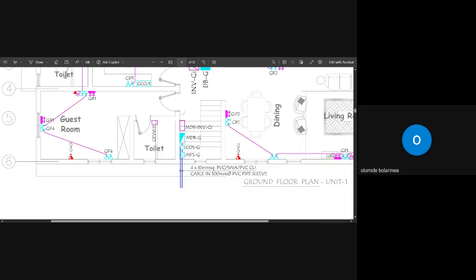Do you see where they wrote our metering system? You know that mostly our meter is not usually inside the building. Yes or no? Yes, most of the meter installed is usually outside. But in this case, I will put my metering system at that staircase area because of what? Number one, aesthetics. And because I can't just put a metering system here with my wire. So let's just put our metering system here.